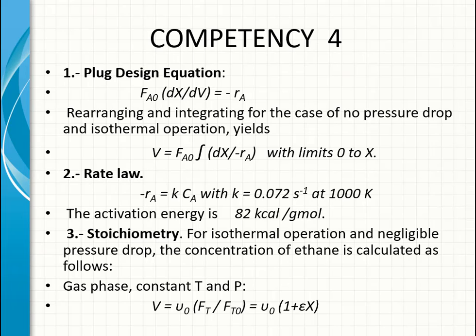Now we come to the flow design equation. For the flow design equation, we had that from the mole balance, FA0 dX divided by dV equal to minus rA.